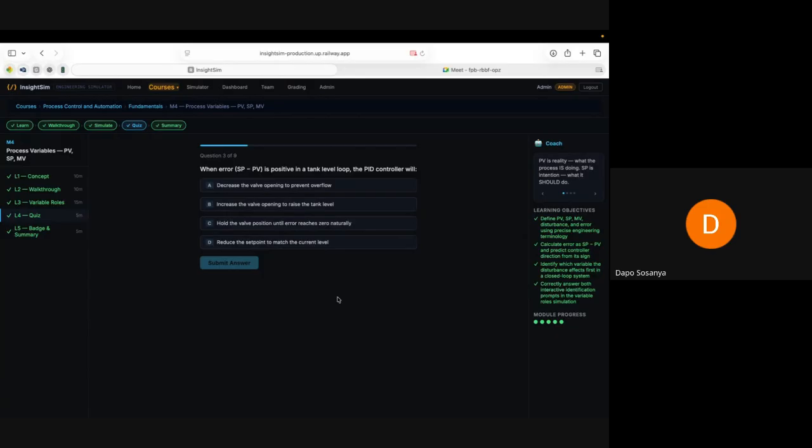I think I know where you're coming from: there is no output from the tank, right? But in reality, the valve at that output might be passing, meaning there might be some leakage, and it has to be maintained. Don't look at the value of the MV. The controller has calculated that keeping MV at 50% ensures that SP minus PV equals 0.